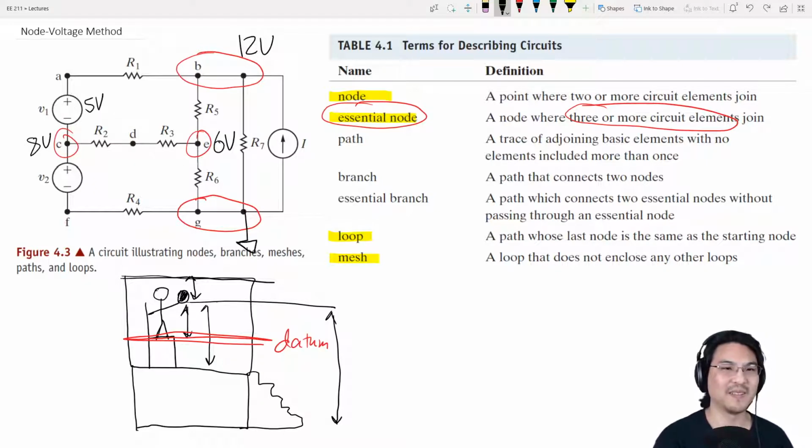See the plus sign here? That means this is higher than this. That's maybe physically impossible. Let me make it 2 volts. So this is higher than C by 2 volts. So over here would be 10 volts. Then here to here has got to be 2. And then let's say this voltage source is 3 volts. See the plus here and the minus here. That means this is 3 volts less than here. So it would be 5 volts over here. So then here to here, 5.